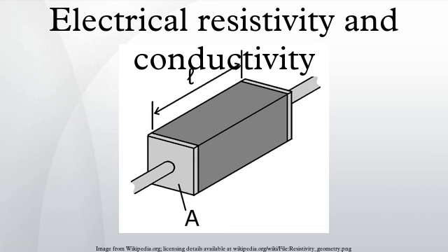For example, for long-distance overhead power lines, aluminium is frequently used rather than copper because it is lighter for the same conductance. Silver, although it is the least resistive metal known, has a high density and does poorly by this measure. Calcium and the alkali metals have the best resistivity density products, but are rarely used for conductors due to their high reactivity with water and oxygen. Aluminium is far more stable. Two other important attributes, price and toxicity, exclude the best choice, beryllium. Thus, aluminium is usually the metal of choice when the weight of some required conduction is the driving consideration.